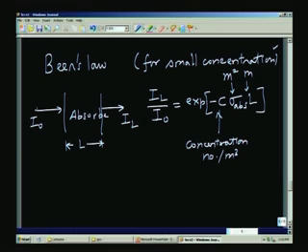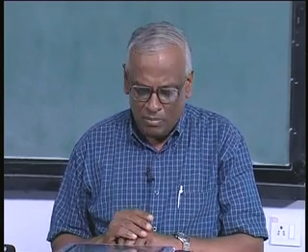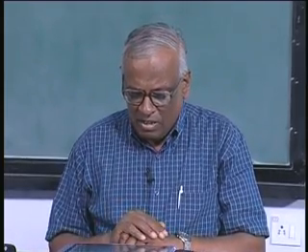In this case, we are looking at a particular wavelength at which some absorption is expected of a particular gas which is existing in some concentration within that medium. There may be other gases present which are not going to be influencing the absorption process. For example, if you remember, I talked about the lambda on and lambda off.